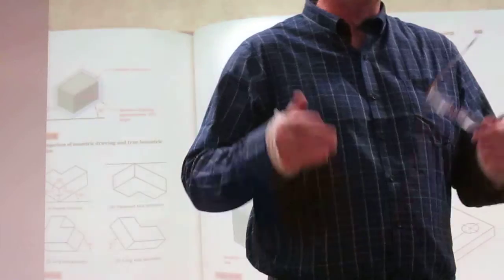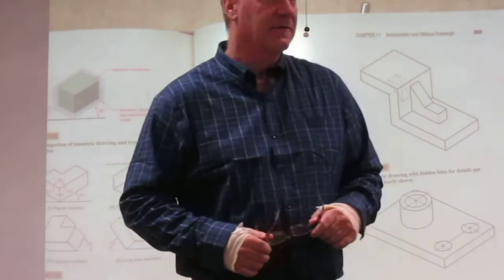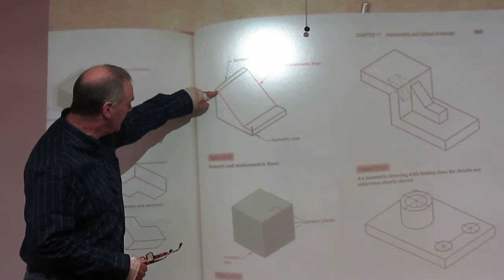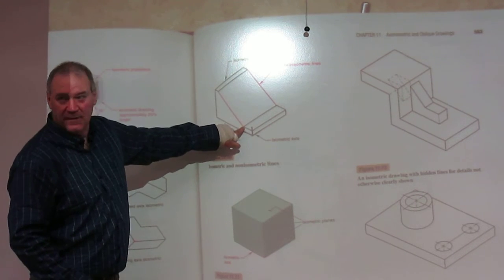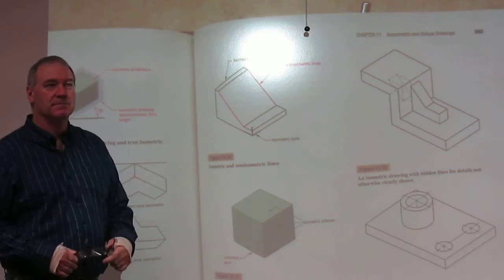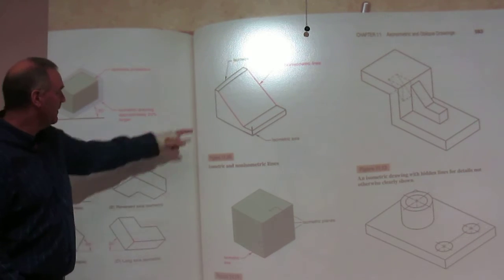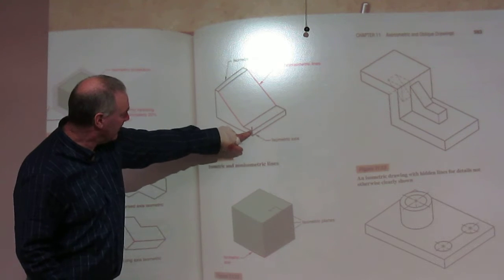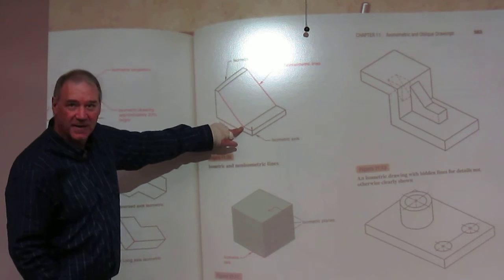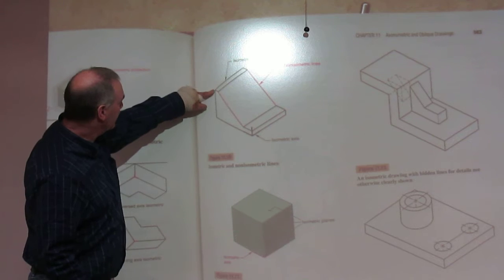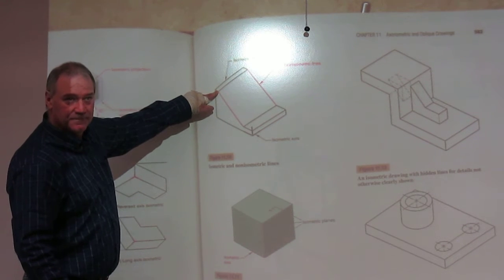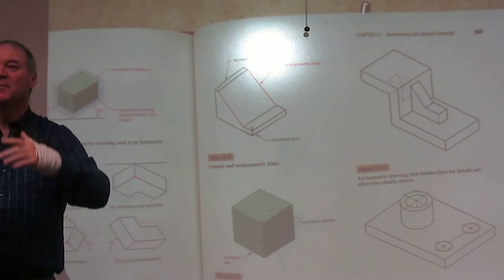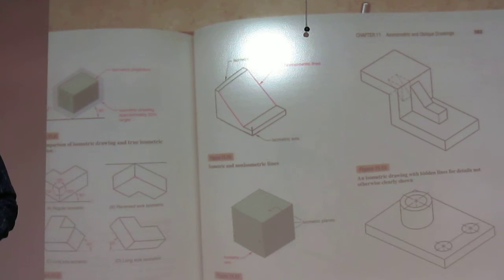Because remember, you got full scale receding axes. Find those endpoints on your receding axis line. So I find that endpoint and that one, then I can draw the line. What endpoints? The endpoints of the line. So right there, that one and that one. Because you can measure right along that line, right? You can measure up and over and find that point. I can measure over and find that point along that one. Remember, we start with a full cube, totally encompassing thing, and then we start removing items when we're drawing these.